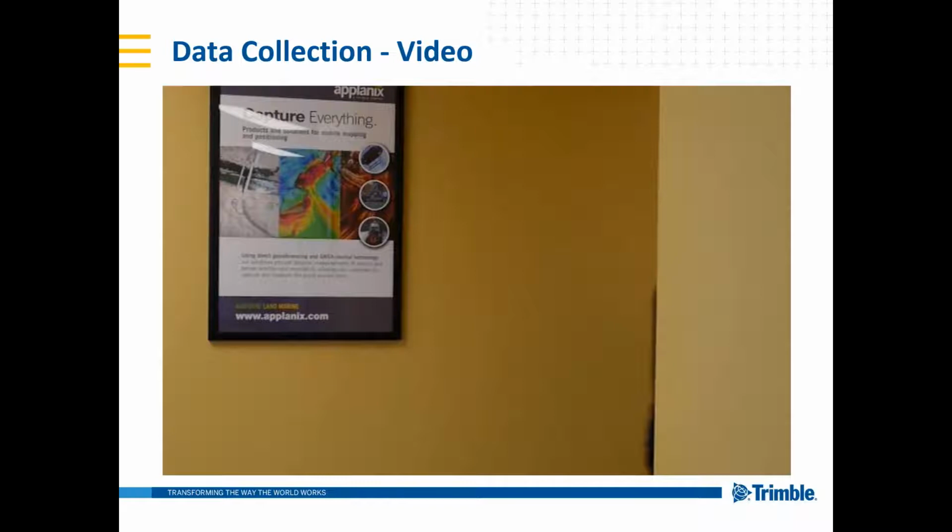Question about, sorry, that top one there. Assuming it's better to close each room door as you scan within the room. That's actually not true, because, well, I guess it depends on your requirements for the scan. If you want to see what the room looks like with the door shut, then yeah, you might want to close the doors behind you. But from an accuracy and scanning point of view, you want to be able to see the rooms outside the room you're in, just to make sure that everything is locked together and there's no possibility of misregistration from one room to the next.